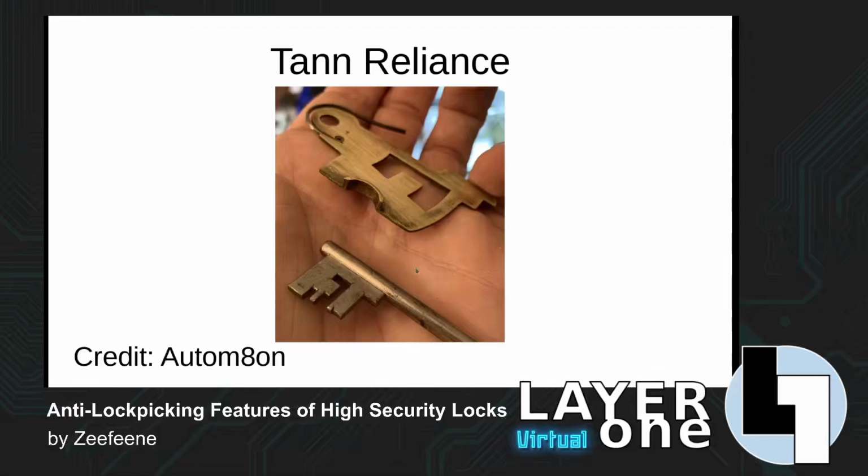And the problem that you've got here is that traditionally, if you were going to attempt to pick a lever lock, you have a wire that simulates typically the end of the key, and that gets inserted into the lock and is used to try to retract the bolt. And when the bolt stump then presses against the levers, we would use another pick wire in order to manipulate those levers into the correct positions. But that is an L-shaped wire, and that would simply not be able to get around this L-shaped ward. So we'd have to come up with some more complex design, possibly involving multiple pick wires with intricate bends in them in order to get around that L-shaped piece of warding inside the lock.